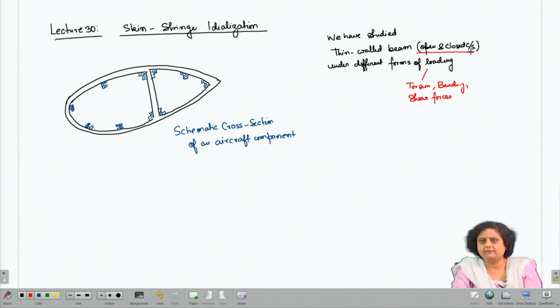So, this information will later help us to design the beam, to see whether the maximum stress, be it normal stress or shear stress, including the factor of safety, is below the ultimate or the allowable strength. So, if the maximum stress is below the allowable stress, including the factor of safety, then we said that the beam design is okay and it can be implemented.